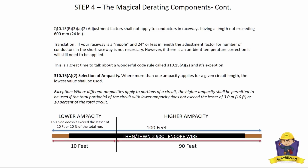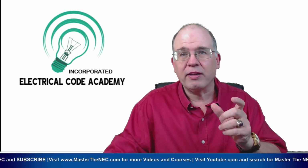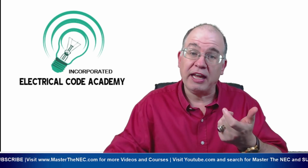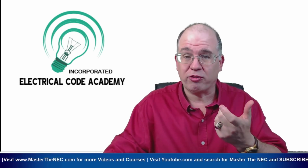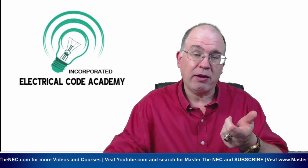The next one we're going to talk about is 310.15(B)(3)(a)(2), which says the ampacity adjustment factors shall not apply to conductors and raceways having a length not exceeding 24 inches. So this is the nipple rule. So if I have a nipple that's 24 inches or less, or a raceway, it's still a raceway, that's 24 inches or less, or it could be a cable that's 24 inches or less, then I don't have to apply the adjustment. Okay, we're in the adjustment now.